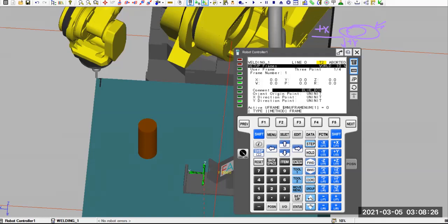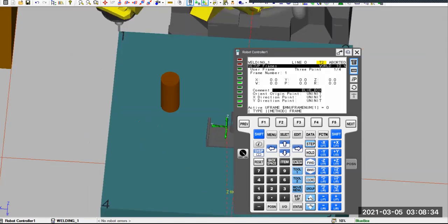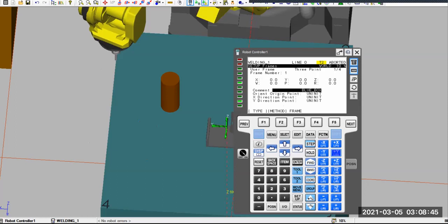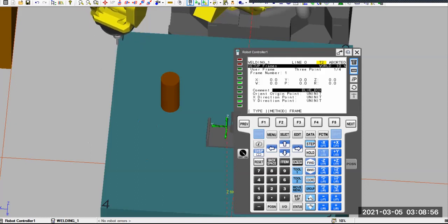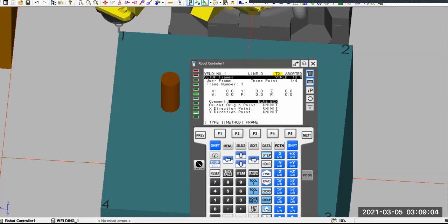All right, so I will jog to verify and let you know if I'm right. We want to go from corner 1 to corner 4, so we have to jog in world positive Y, right? So this is positive Y, not the X. All right. If we go back with minus Y, back to the corner. Now if I ask you from corner 1 to corner 2, so this is corner 2. If you want to move from corner 1 to corner 2, again, review of the right hand rule, it's supposed to be minus X, right?